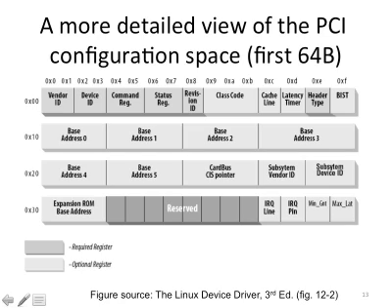To know the size of the buffer, to understand the status of the buffer within that PCI interface, we need to map that resource into the host address space. Because the CPU only knows about its own address space, from 0 to 4 gigabytes, or larger if it is 64-bit. So whatever resource is presented by the PCI device, if you want the host CPU to access that resource, it has to be mapped into the address space of the host. Could be memory address space, could be I/O address space. So that base address is going to be stored in these registers.